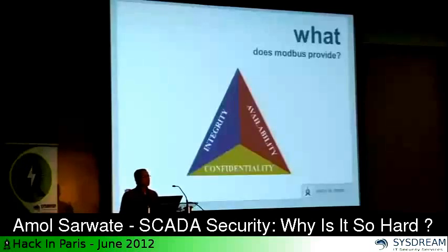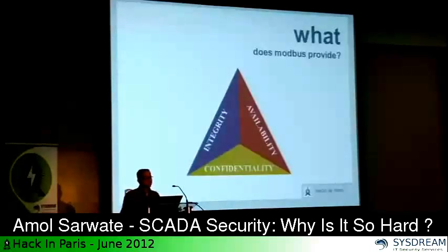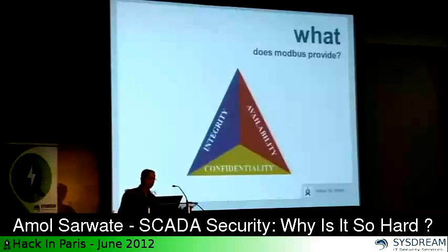So we decided to look at another protocol called DNP3. How many people have heard this sort of weird name? It's a protocol that was designed from the ground up for electrical transmission lines because it has a lot of good things over Modbus. What Modbus has is the client has to constantly poll, as in ask, hey, what is the temperature? What is the pressure?